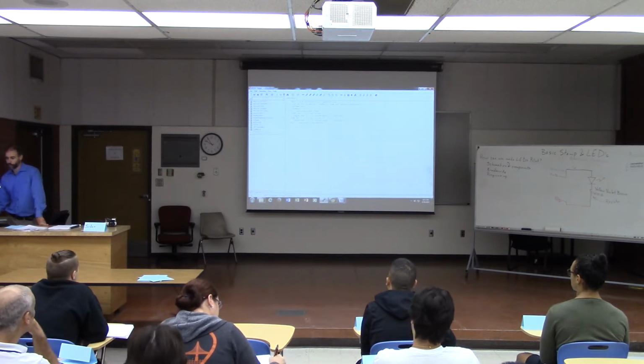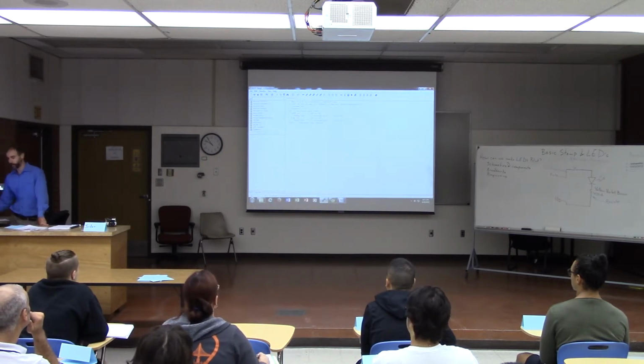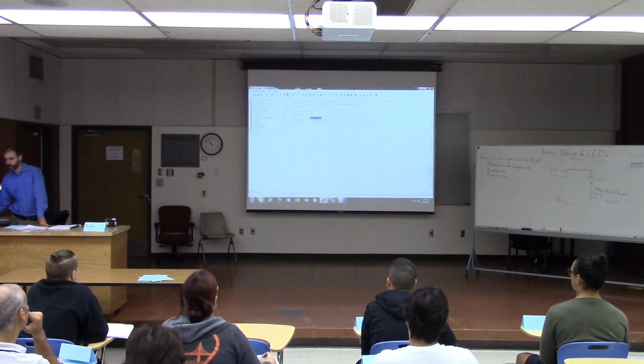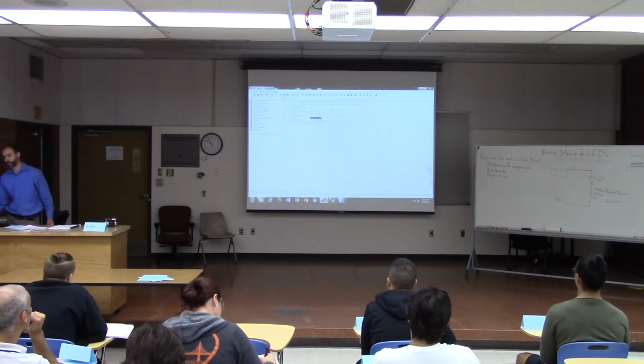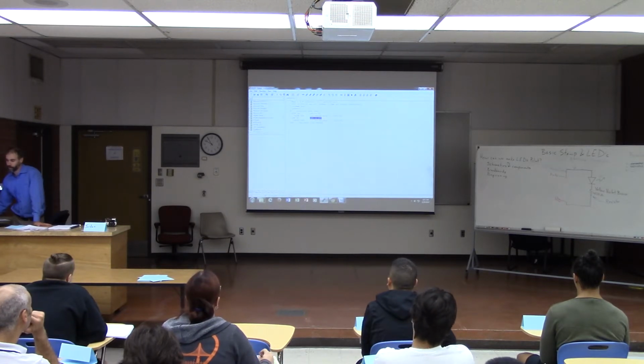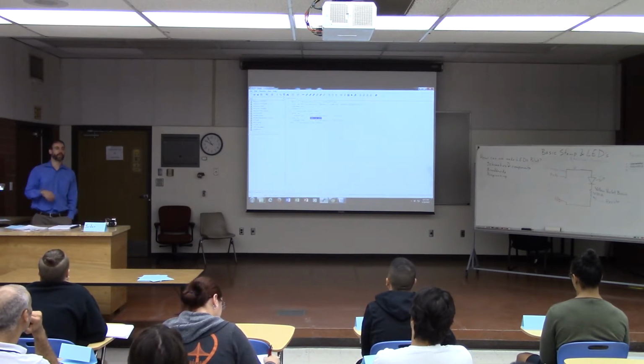Now we say low 14. Well, high 14 turned the electricity on, so what do you think low 14 does? Turns it off, exactly. And then the note confirms that. It says turn LED connected to pin 14 off. And then another pause. Okay? So we're turning the LED on, we're waiting, we're turning it off, and we're waiting. Right? That looks like a blink to me, right? Turn on, wait, turn off, and then repeat.